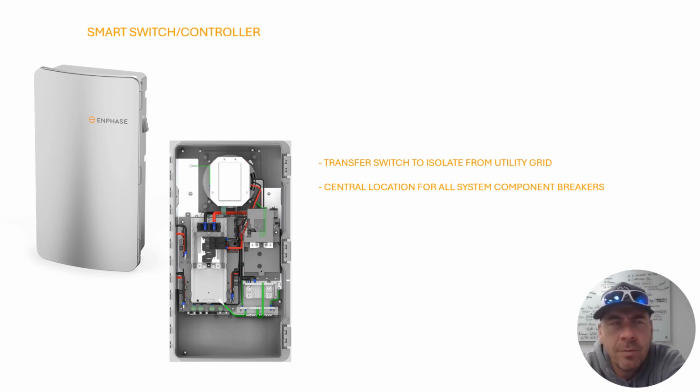This enables us to still have power on the residence for the backup loads and to prevent power from coming from the backup system, or microgrid as some people like to call it, keeping it safe for people working on the grid or the electric main service panel, etc.